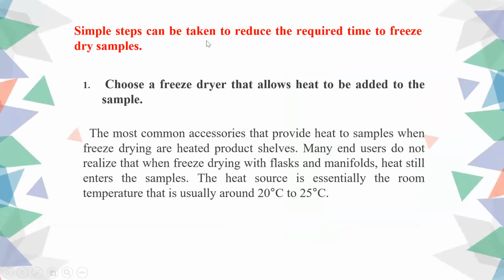As I said before, the time required for freeze drying is approximately 50 hours or longer, depending on the sample characteristic and the type of freeze dryer. So there are simple steps that can be taken to reduce the required time to freeze dry samples. Number 1, choose a freeze dryer that allows heat to be added to the sample.